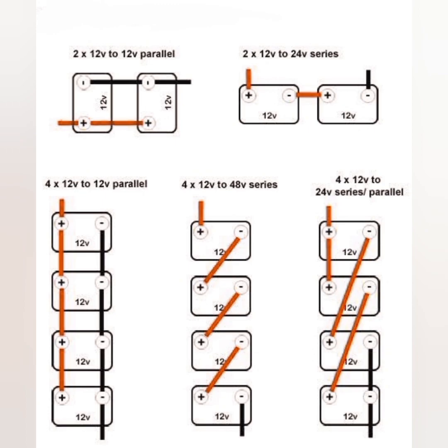Here, in the series parallel, just see the slide. Series parallel connection, 24 volt series parallel. Here 4 batteries, 12 volt batteries, are used, that is converted into 24 volt when we connect in a series parallel combination, and the ampere hour of this battery will get increased.